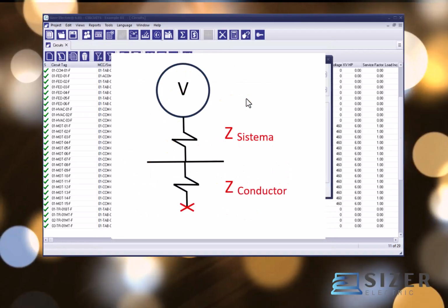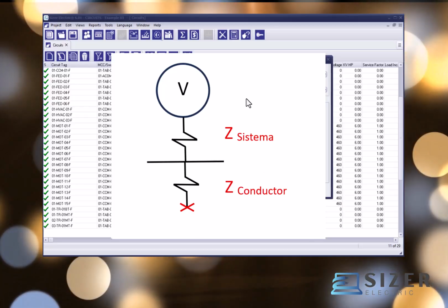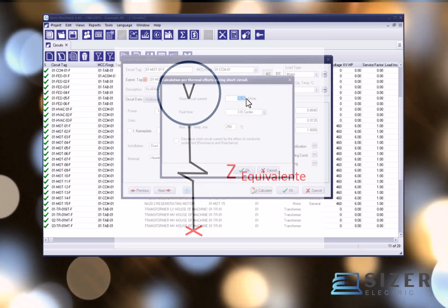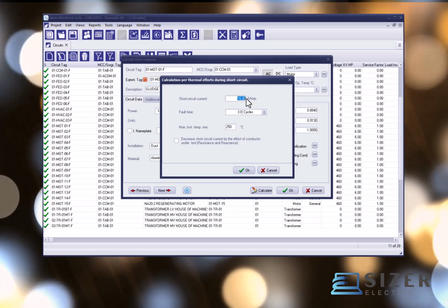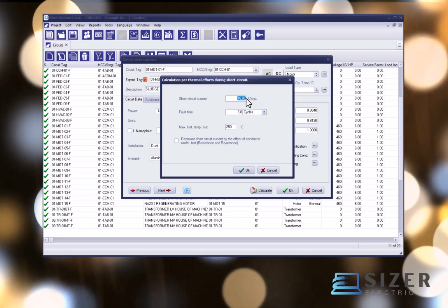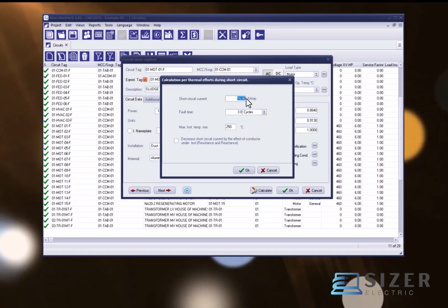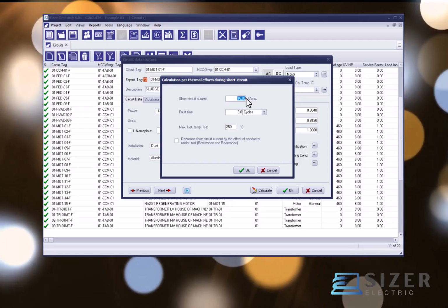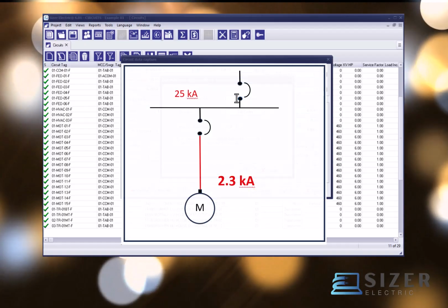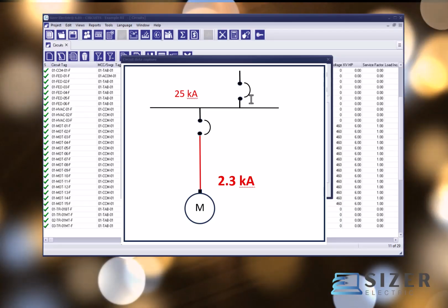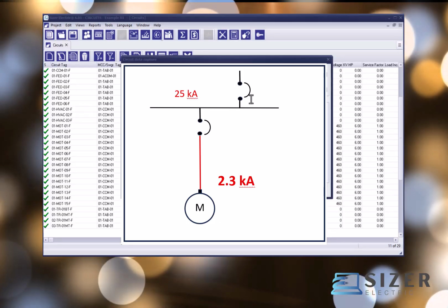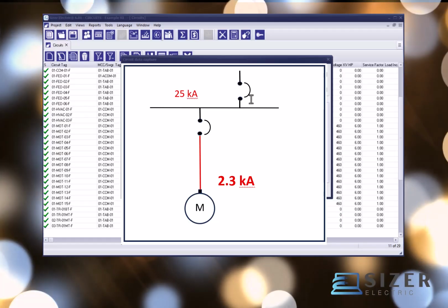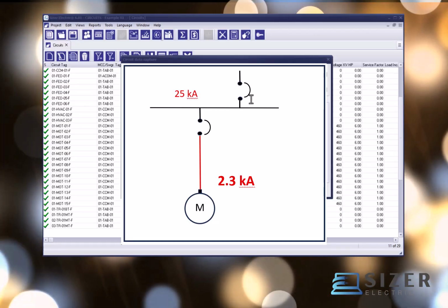The software assumes an infinite bus analysis and applies a Thevenin equivalent impedance model to determine the reduced fault current at the load end. Details of the formulas used for Thevenin resistance and reactance reduction can be found in the help section by pressing F1. If a detailed short circuit study is available, providing fault current values at both the main bus and the load terminals, and including information on upstream and downstream fault current contributions, the currents flowing through the conductor must be analyzed to determine the maximum fault current to be used for conductor validation.